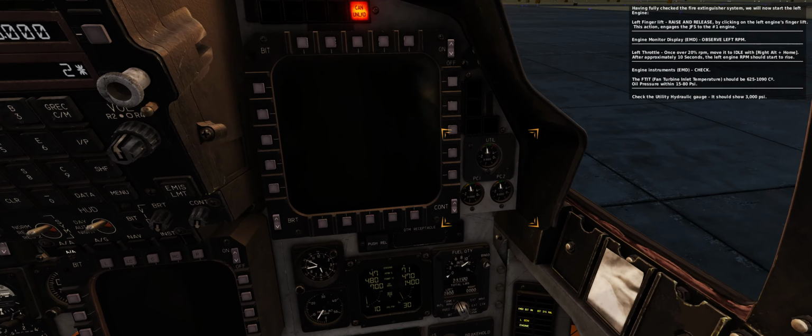The navigation with forward-looking infrared capabilities are delivered by the AAQ-13 navigation pod. It provides infrared, forward terrain video on a HUD display, in support of the terrain following radar operation, not available in early access. The navigation pod has to be installed on the jet, in order for the pilot to be able to use the nav FLIR capabilities. Do not confuse with the targeting pod's TGP FLIR, which is turned on at the rear cockpit.